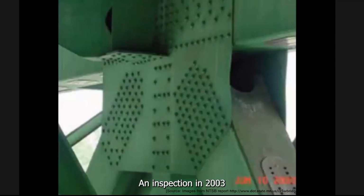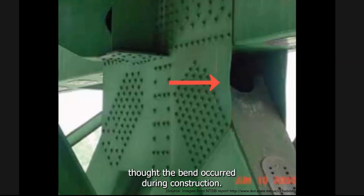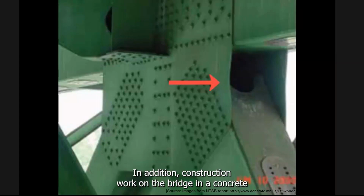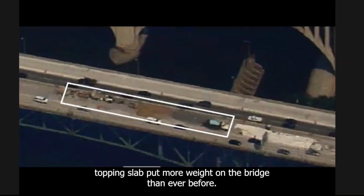An inspection in 2003 found that the gusset plates were bowed, but engineers thought the bend occurred during construction. However, a design error in the gusset plates left them thinner than they were supposed to be. In addition, construction work on the bridge and a concrete topping slab put more weight on the bridge than ever before.